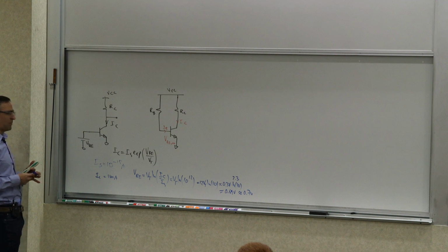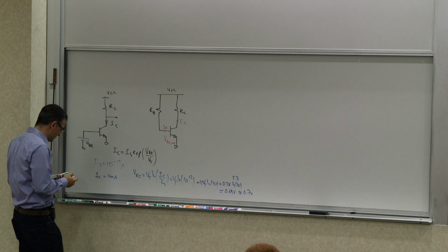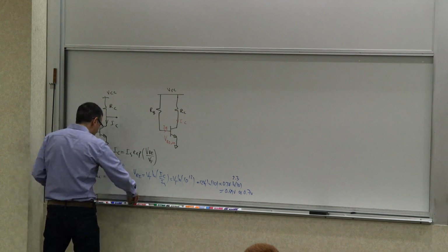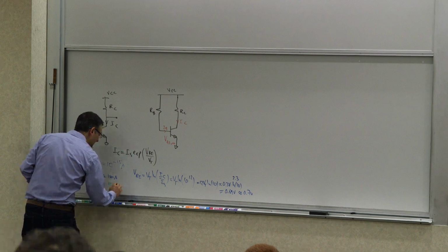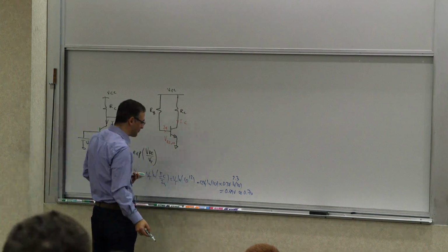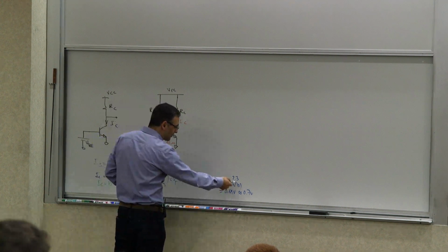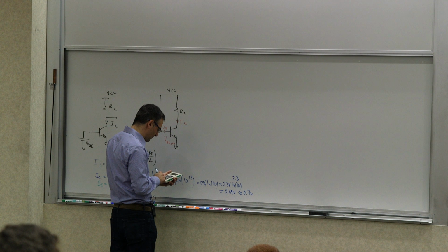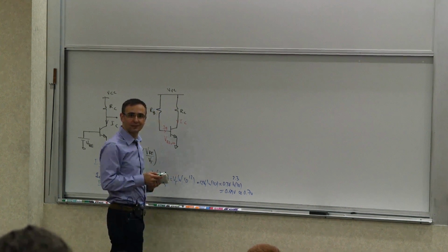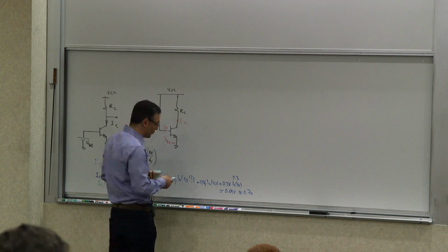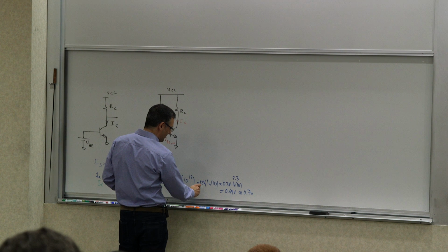You may say, well, but if I'm not operating at 1 milliamp? What if I'm operating at 10 milliamps? Well, if you're operating at 10 milliamps, all of this would be the same. This would be 10 to the 13, right? So you add 25 times 2.3 to this whole thing. You add 57 millivolts to it, right? You can do the number directly, but essentially, instead of 12, this becomes 13.